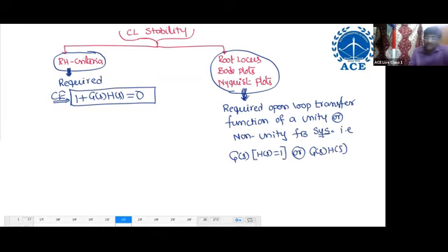So to find closed loop stability, the RH criteria requires the characteristic equation, whereas root locus, Bode plots and Nyquist plots require G(s)H(s). So why not use the characteristic equation here also? It is very difficult to draw a diagram using the characteristic equation.